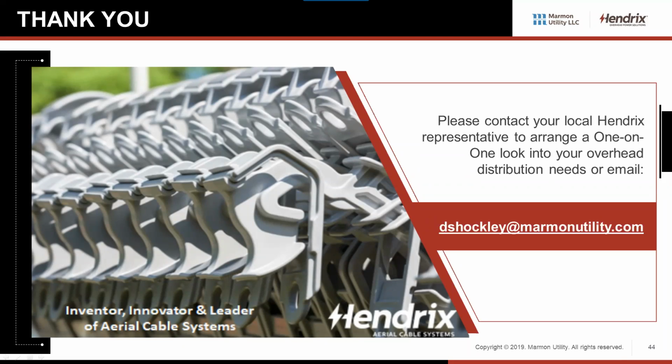So the first one is a simple one. What's the length of the tangent brackets? We've got two different tangent brackets available. Our standard 15 kV is we call it a BM14. Our engineers traditionally haven't gotten overly creative, so it's a 14-inch bracket. For 25 all the way up to 35 kV systems, we recommend our BM24, which is, as you guessed it, 24 inches long.